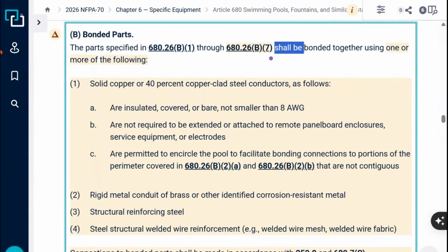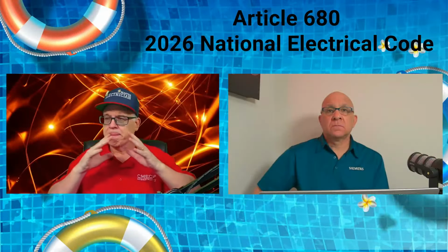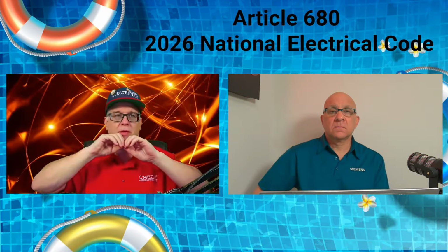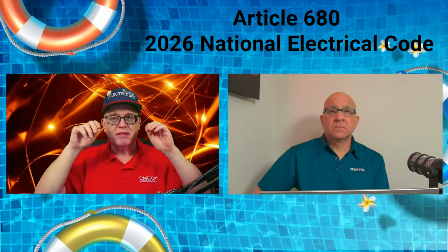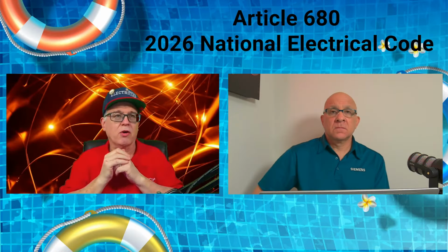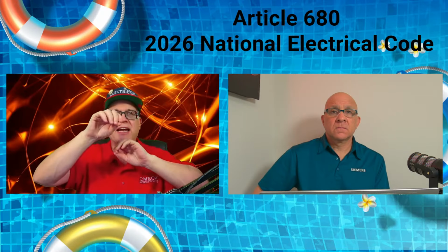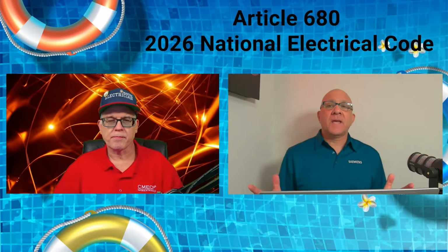So I think one misconception that we'll throw out there real quick before I even get started is that some people think you can't daisy chain things together, or they think you have to do a star pattern where you come away from the conductive pool shell and go out individually to each thing that would need to be bonded. It's not really what it's saying. I could run a single conductor and connect things together, or I could run individual bonding conductors, which is totally different than the things having to do with the equipotential grid. These are connecting things together.